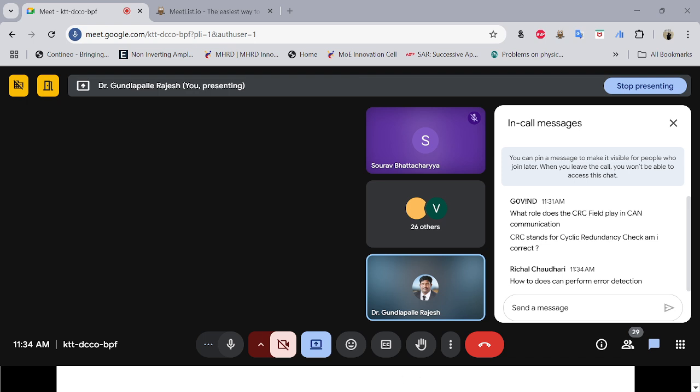Competing nodes switch to receiving, so only one node transmits at a time. Then the nodes that lost the arbitration will start a new arbitration as soon as the bus is free for access again. So no message gets lost in this process.